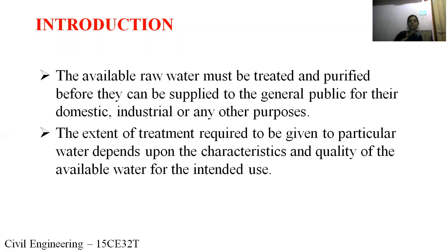In plain sedimentation, again classification has been done. So that is horizontal flow type tanks, vertical flow type tanks. Again, horizontal flow types are classified into rectangular tanks with longitudinal flow and circular tanks with radial or spiral flow.